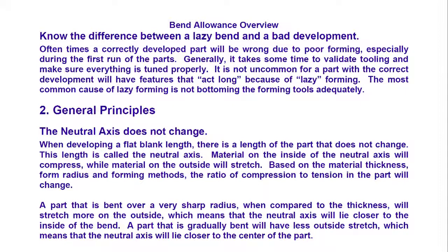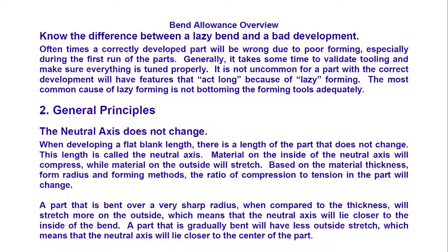difference between a lazy bend and a bad development. You have seen that, no? I think I will leave you to read the first para yourself, my voice I will avoid. Take some time to validate tooling and make sure everything is tuned properly. Not uncommon, but a part with the correct development will have features that act long because of lazy forming. The most common cause is not bottoming the forming tools adequately. Eventually, they will tell you about what is bottoming, what is coining, what is air bending, 3 things.